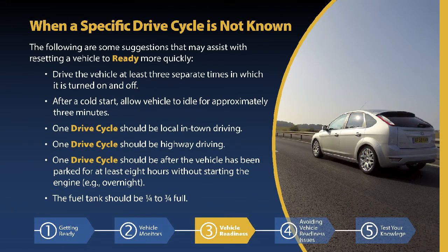The following may assist with resetting a vehicle to ready more quickly. Drive the vehicle at least 3 separate times in which it is turned on and off. After a cold start, allow the vehicle to idle for approximately 3 minutes. One drive cycle should be local in-town driving. One drive cycle should be highway driving. One drive cycle should be after the vehicle has been parked for at least 8 hours without starting the engine, for example, overnight. The fuel tank should be 1/4 to 3/4 full.